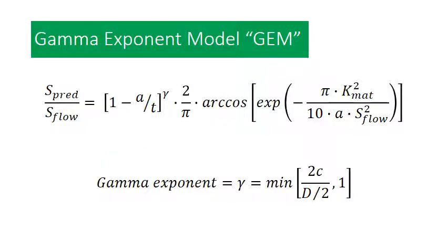So here's a gamma exponent model, which I've nicknamed the GEM. You'll see that it has a very similar mathematical form to the original log-secant model that was developed by the NG18 committee at the Battelle Institute in Columbus, Ohio, back in the early 1970s. However, the NG18 equations tend to be mathematically based on length. In the development of the GEM, I've focused all of the effort on looking at depth, and that makes a big difference.